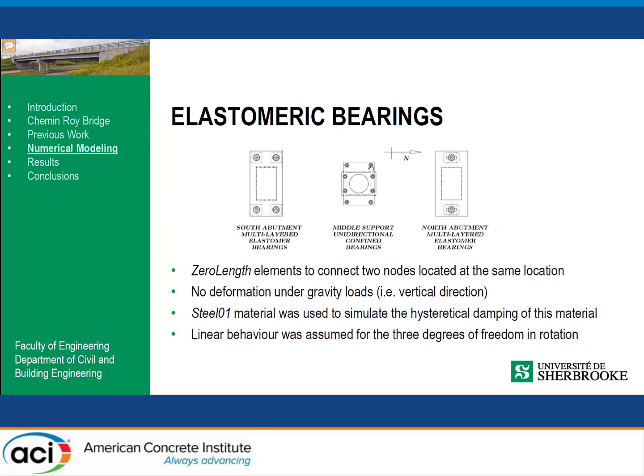For the elastomeric bearings, we use the zero length element to connect the two nodes located at the same location. Here we consider no deformation under gravity loads. We use the steel zero material to simulate the hysteretic damping of this material. And also linear behavior is assumed for the three degrees of freedom in the rotation.